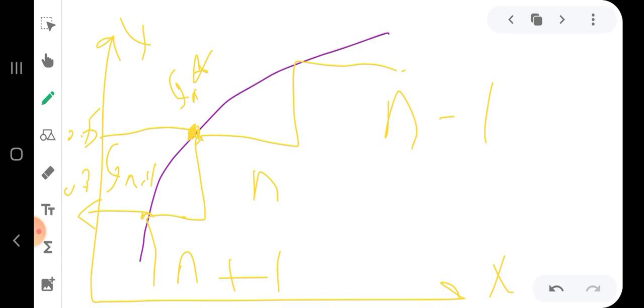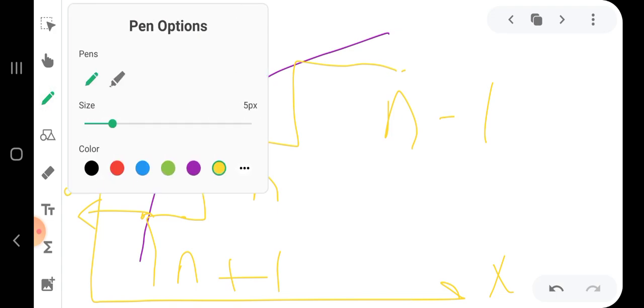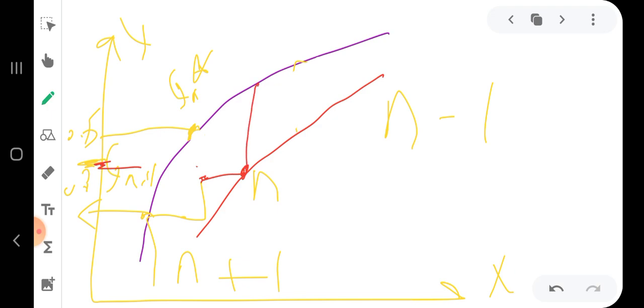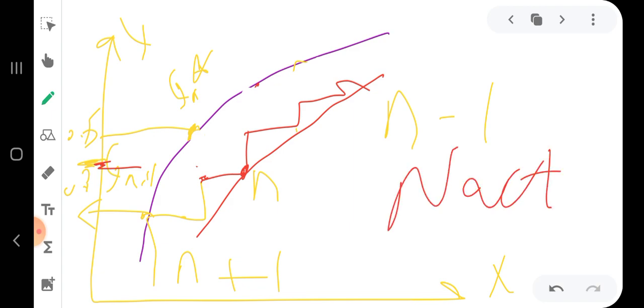So you will go and see where 0.5 is. It is somewhere here. You say, I'm going to stop at this point, and then I remove this extra part and draw these stages again, and then stop here again. Of course, we have the operating line here, and then we move up, remove the extra line, and continue like this until we count the actual number of stages. So that's it.